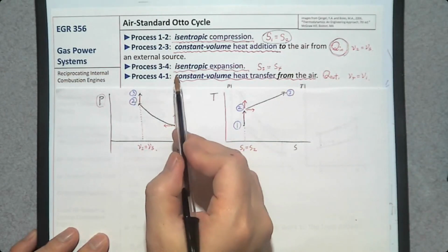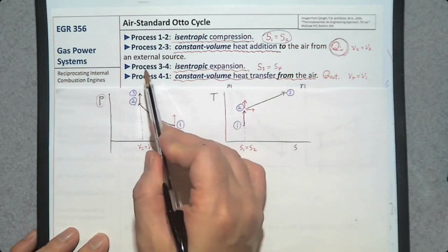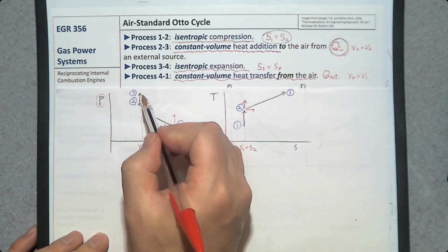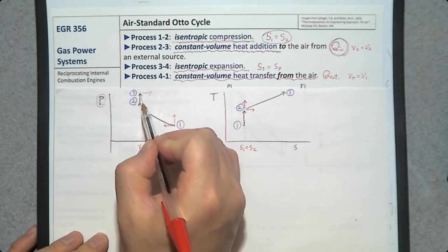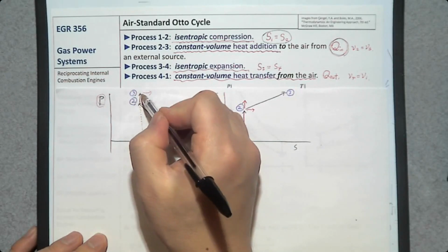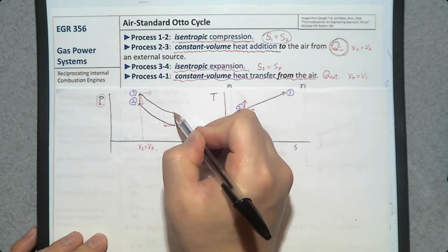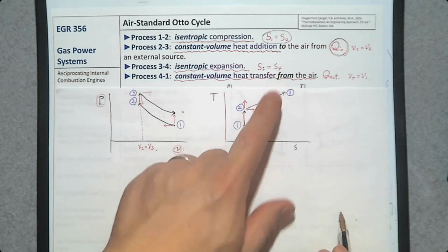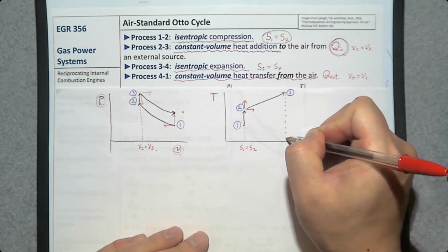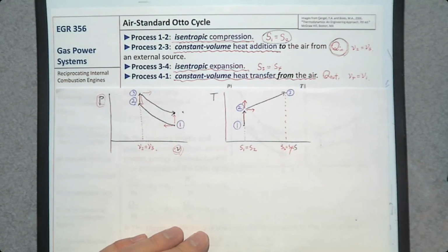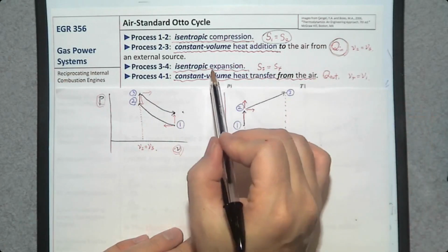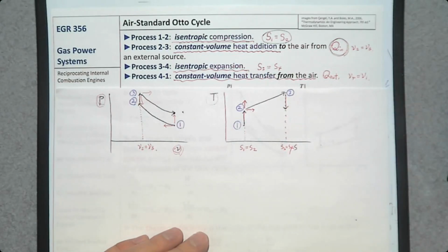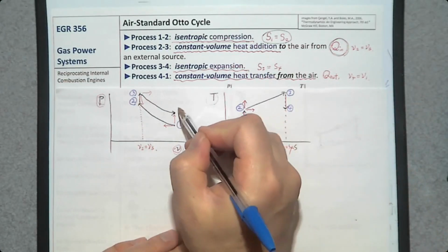And we have an isentropic expansion, process 3 to 4. This is an expansion process, therefore volume should increase and pressure should decrease. So process 3 to 4 is going to be here. On this TS diagram, entropy S should remain constant. S3 should be the same as S4, and it's an expansion process, temperature should decrease, therefore this way. So there's number 4 and number 4.